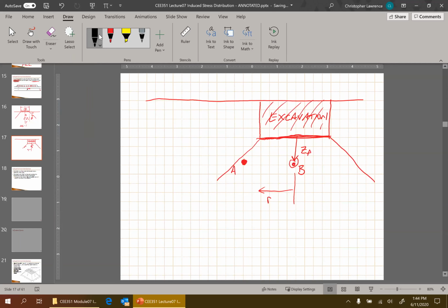On that plane, so this is maybe in plan view, some rectangular excavation. But on that plane that I just colored in black, there used to be some load caused by the weight of the soil above it, the weight of the soil in the excavation. When that excavation soil was removed, that plane experienced a negative Q. It used to be higher than what it is right now.